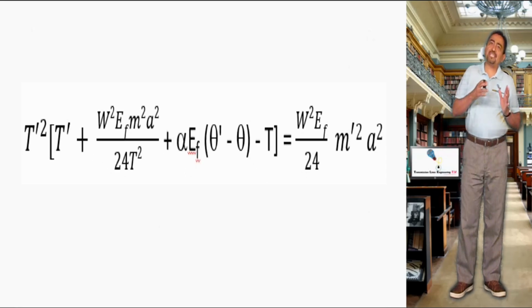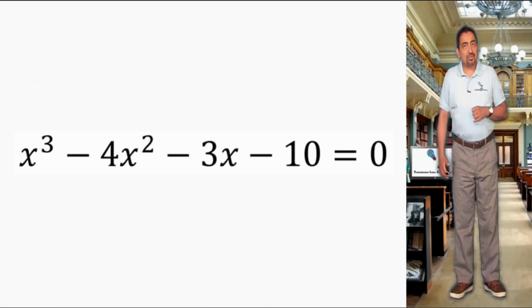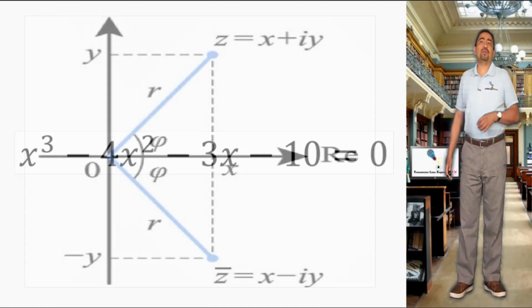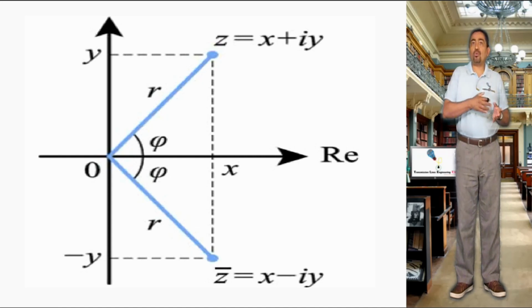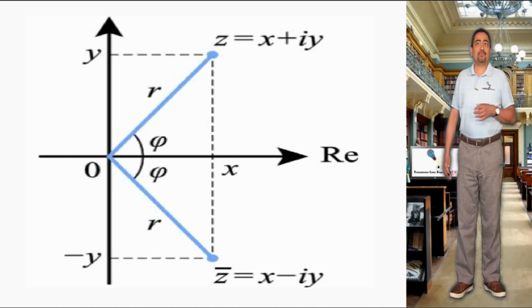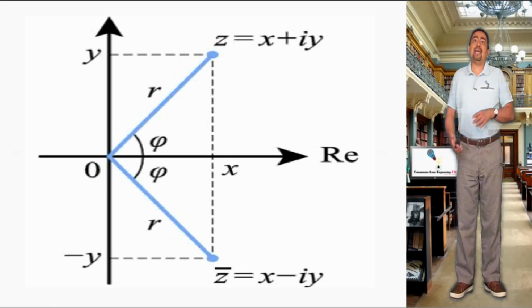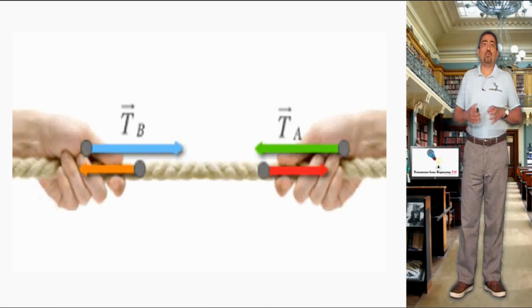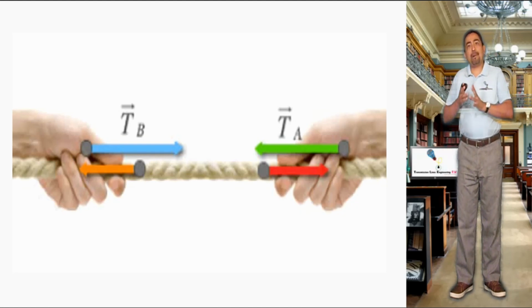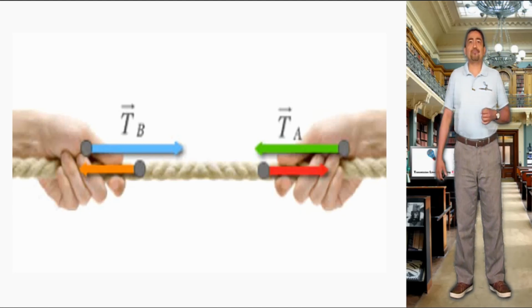The change of state equation is based on a third-degree equation, or a cubic equation, which has a complex root, a complex or imaginary number, a negative root as well, and another positive real root, which represents the value of the cable axial force in question.